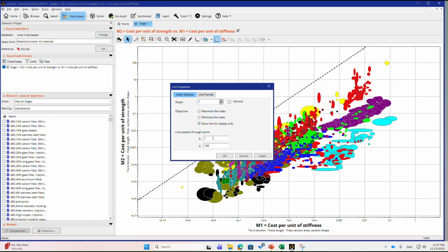Keep in mind that you are plotting this on a log-log chart, so these numbers need to be applied exactly in the same manner. For the coupling constant equation, always keep your x as 1, and then y should be the value of the actual variable cc that you have determined.